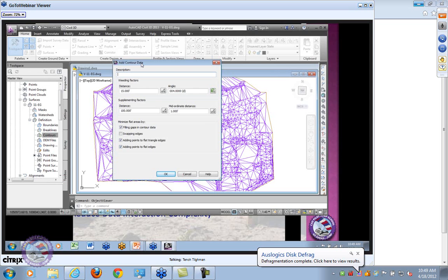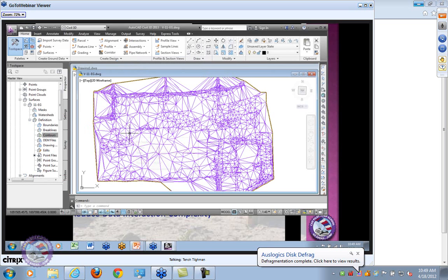It processes it once as pure points at every single node that it discovers, and then it adds break lines in between all those points. So it's really doing the points first and adding break lines that follow along those within a certain set of rules. That's what contour data is. Well, we actually need an AutoCAD object to do it that way.